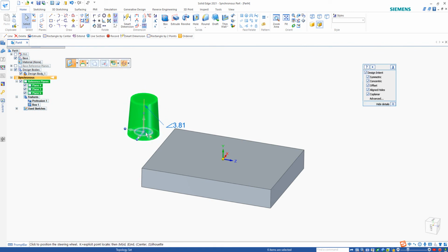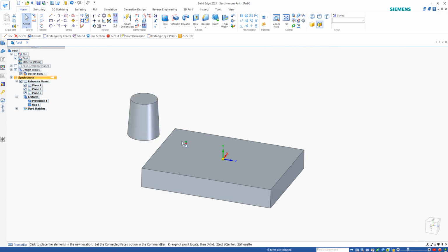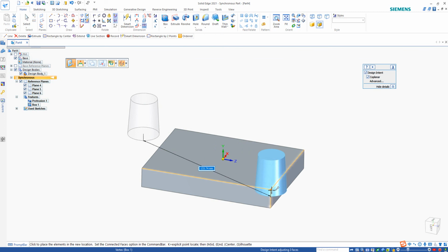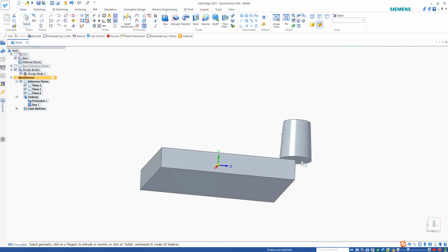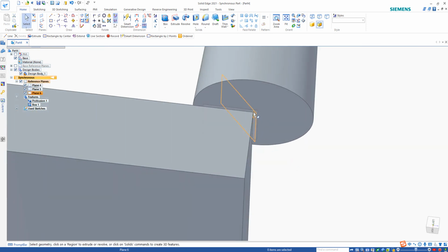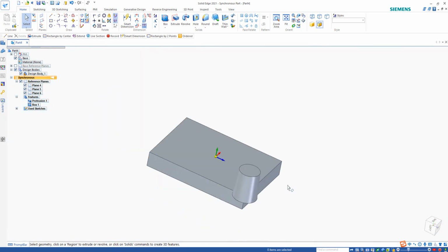Let me do it one more time. Move the steering wheel to the bottom, pick the ball, aim at a vertex, and then pull the handle towards the vertex, and make sure these two are aligned. When you see this white sticker, that means these two features are aligned. So now you can release the button. Now the vertex is aligned with the center of the bottom.